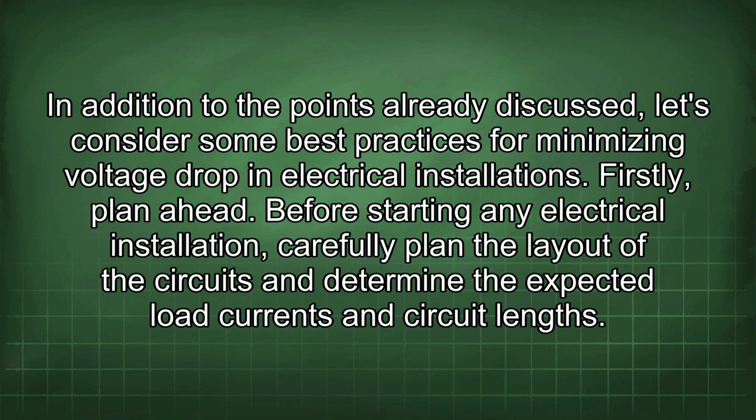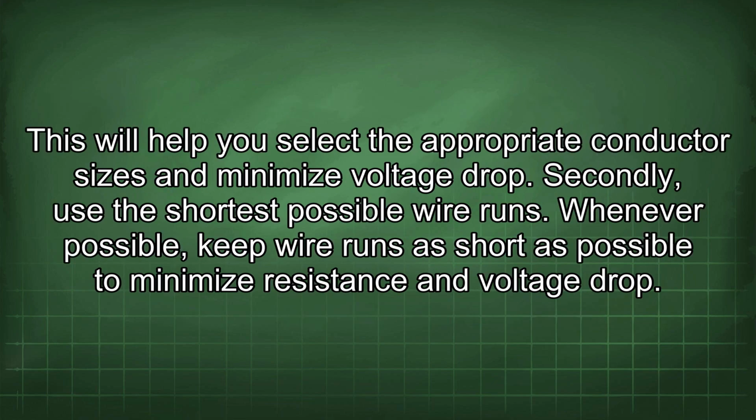In addition to the points already discussed, let's consider some best practices for minimizing voltage drop in electrical installations. Firstly, plan ahead. Before starting any electrical installation, carefully plan the layout of the circuits and determine the expected load currents and circuit lengths. This will help you select the appropriate conductor sizes and minimize voltage drop.